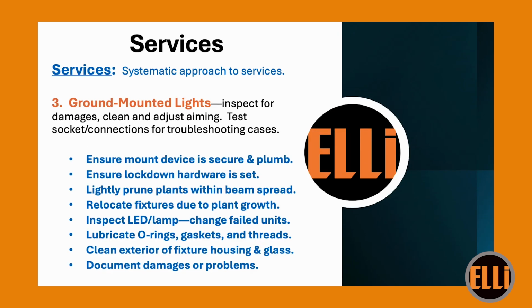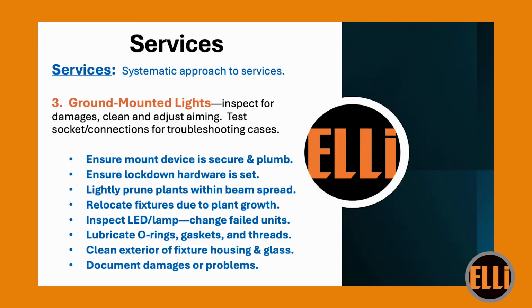Okay? The next item is inspect the LEDs or the lamps. As I'd mentioned in the beginning, you want to make sure they're operating to their best performance. They're not flickering, and all of the LED chips are burning properly. Sometimes they'll start failing after a certain number of years. One of the 3 chips may be burning out, and you'll see that. So just go ahead and change it, put in a new LED at that point, and you're good to go.